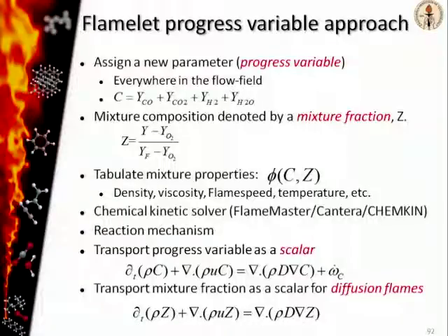And in the course of the fluid dynamic simulations, all you do is look up the properties from these tables depending upon certain parameters that are solved for in the simulation. So say you're at 50% state of reaction, then you look up in the table and you get all the thermodynamic properties such as density, viscosity, flame speed, temperature, etc. for the mixture, and then you plug that back into your numerical simulation. So it's a lookup table procedure where you're tracking the state of your mixture by using just 2 parameters instead of using the entire chemistry. But the entire chemistry is still captured because it's still there in the table that you have created prior to running the simulation.